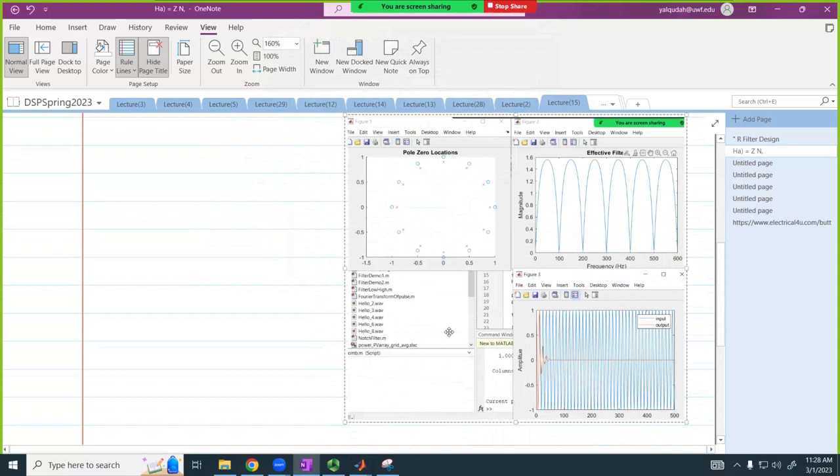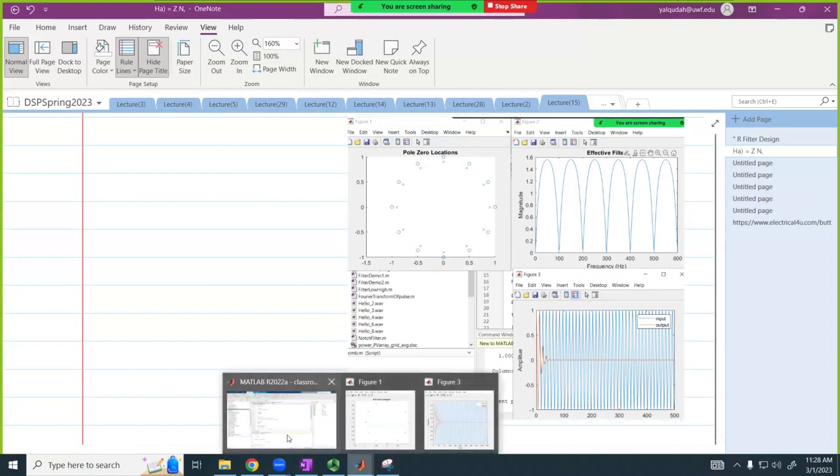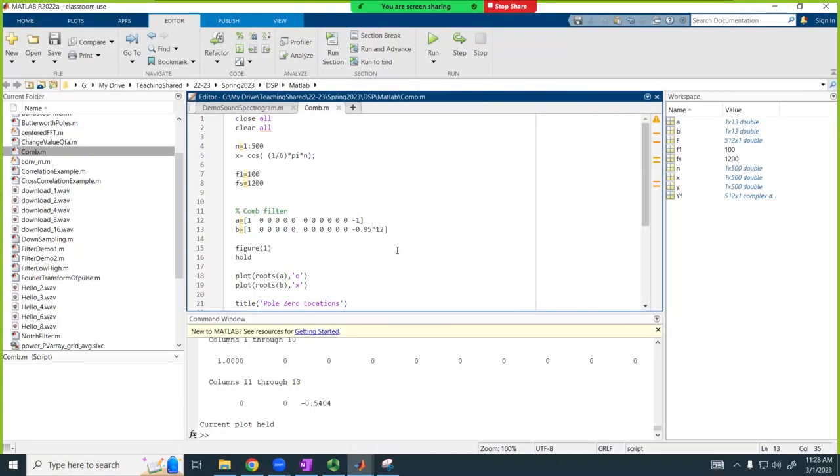So when I do this filter and I need to implement it, how can I choose this value? Why would I not choose 0.99? Or can I choose 0.99? It's too close. It depends on the device you're implementing this on. If there's any rounding and it's going to round the 0.99 to a 1, then I'm not having a filter, because the 1 and the 1 are going to cancel each other.